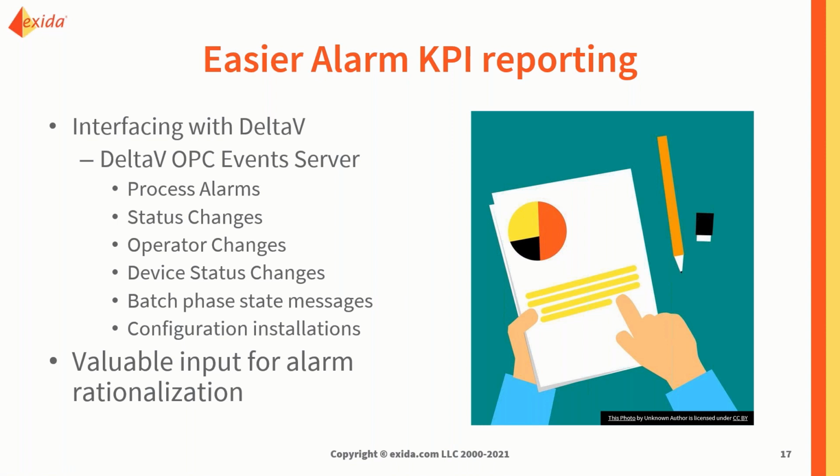And if you need to bridge it to another SCADA system using other PLCs, they can allow this information to flow into another system, or when you try to look at it at a much higher level. This would be very important because all this information listed here are KPIs, key performance indices, of that particular alarm system. And these would be very valuable input for a review of your alarm system, which can be alarm rationalization. So these are very important information.